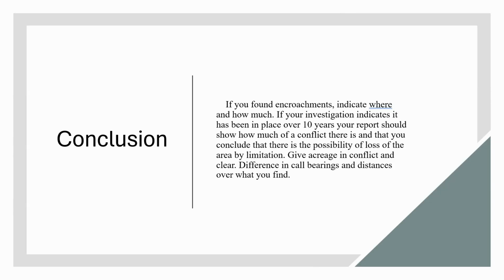If you have acreage that's in conflict, it has clear difference in any bearings and distances from previous records that you found, especially the original survey. All of that information is going to need to be included in that conclusion.